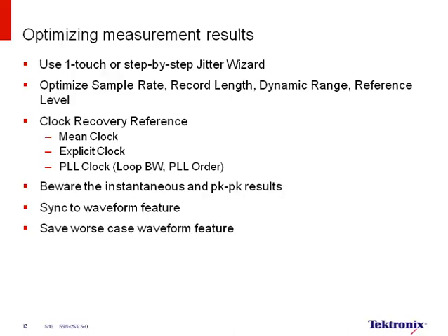Or, for example, if you have something they call a lone bit pattern, you will also see some of these occurring. And then again, some of these tools have the ability for you to save the worst waveform. So if you run an analysis overnight and capture lots of data, there are tools that allow you to save the waveform with the worst failures, so you can go back and see what exactly happened on that specific acquisition.